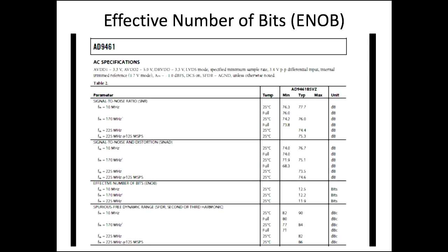So that's the reason you should know about these concepts. Otherwise, when you make a design, you can make mistakes, and you will be scratching your head: why is my ADC output jumping? In a DSO, you might not see that much jumping because you have only 8 bit and your input range is small. You don't have that much tight noise.